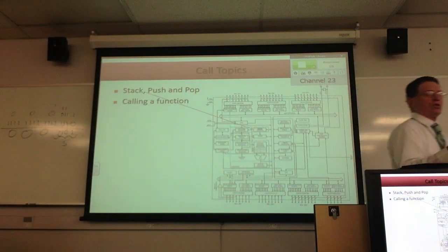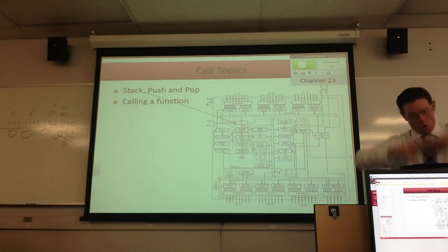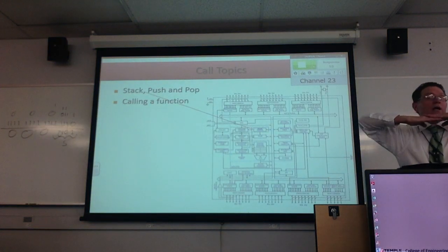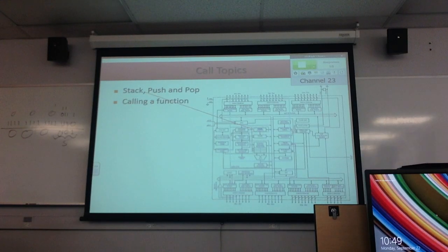As a matter of fact, you used to use the stack for other things. Look at the PIC controllers: their stack is only for subroutines. On the PIC 16 series, you can only call up to 8 subroutines because that's the length of that stack. It's a very small stack. Our stack is physically going to be SRAM all the way down at the bottom, and it's going to work its way up. So you can call as many subroutines as you want, just as long as you don't start overlapping things in there.